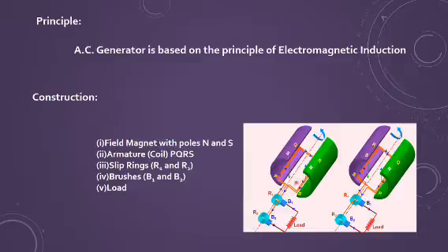The armature coil consists of insulated copper wire, with N number of turns, which are wound on a soft iron core. The soft iron core is not a single block but is split, or laminated, so as to avoid the formation of eddy currents. So you should keep all the previous knowledge in mind and know which material we use for a particular thing, so that you are able to answer if asked in conceptual problems.